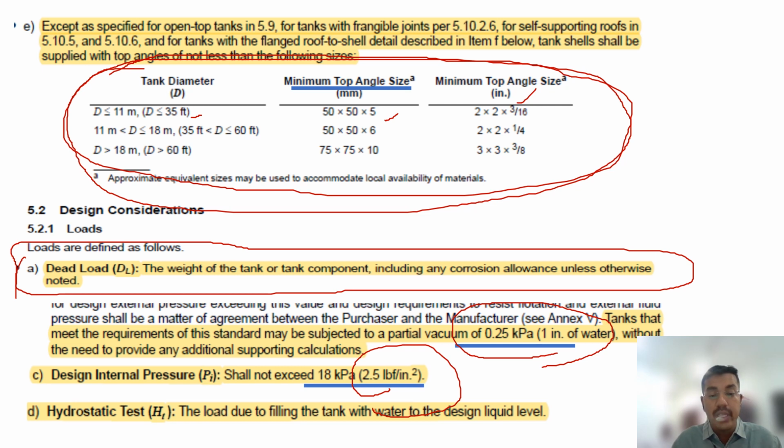Hydrostatic test. The load due to filling the tank with water for design liquid level is called hydrostatic. We will read about the hydrostatic test in further chapters. There is no pressure in this tank. Okay, the tank is not tested with pressure, just atmospheric pressure.